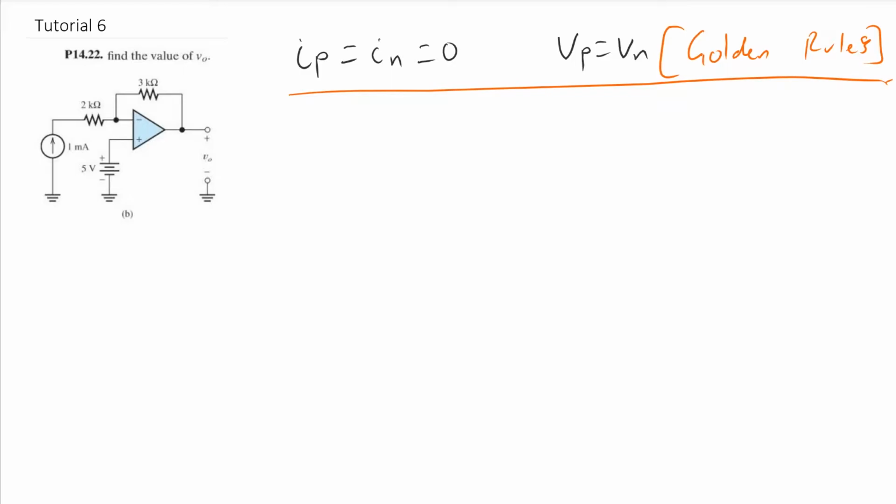The second tip is you normally want to start off these analysis questions by doing Kirchhoff's current law at either the inverting terminal or the non-inverting terminal, depending on the question.